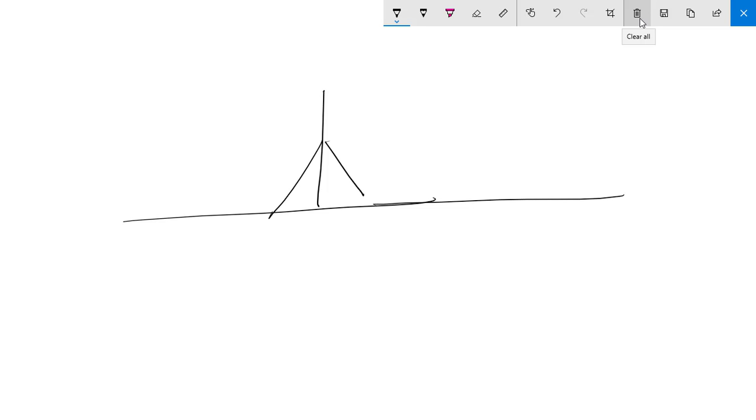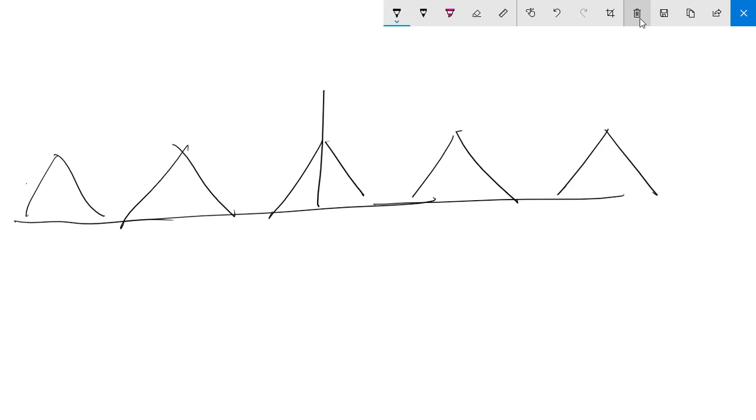In the frequency domain, sampling actually means repetition of the spectrum. So this is our original spectrum. It will be repeated, and it goes on. But we need only this spectrum. We don't need these other things. So what we need to do is cut these spectrums off.